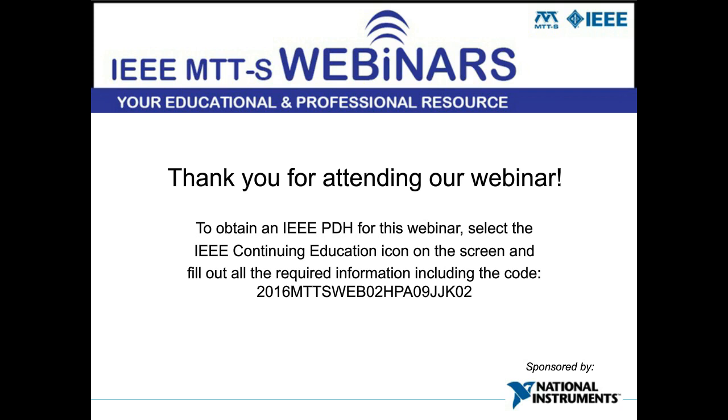So that shows you the trade involved there in terms of volume as a driver for the cost. The other thing is, as time goes on, the big driver in cost for GaN right now happens to be the substrate starting cost. And that keeps coming down. People are transitioning to 6-inch from 4-inch, which basically will halve the cost of the chip. So as time goes on, the cost is going to go down. But again, it's really specific. You have to tell me frequency and power level, and then I can tell you what the various technology trades are in terms of cost.